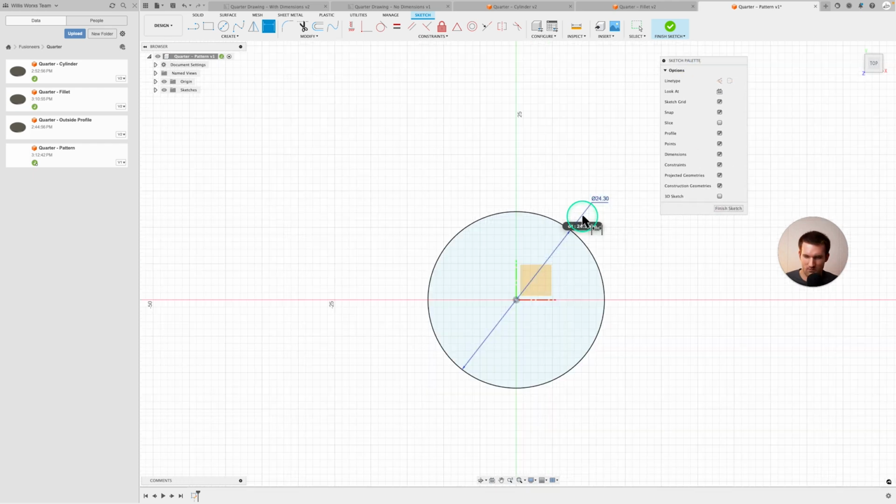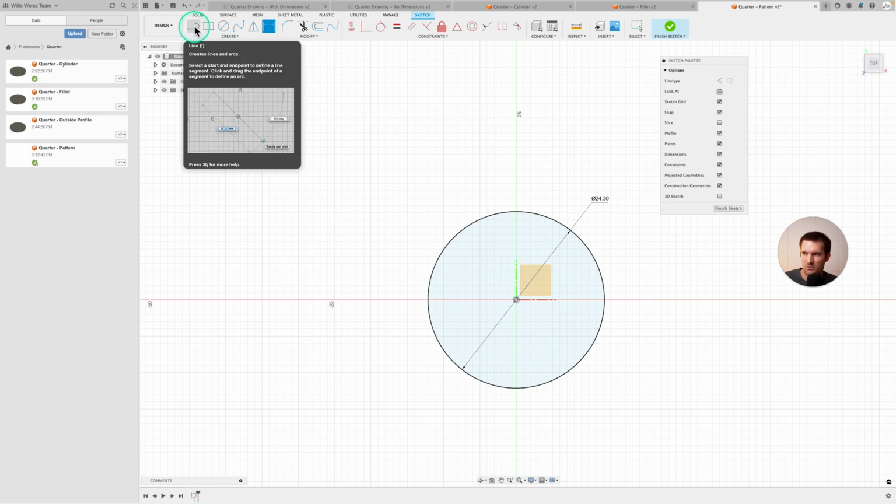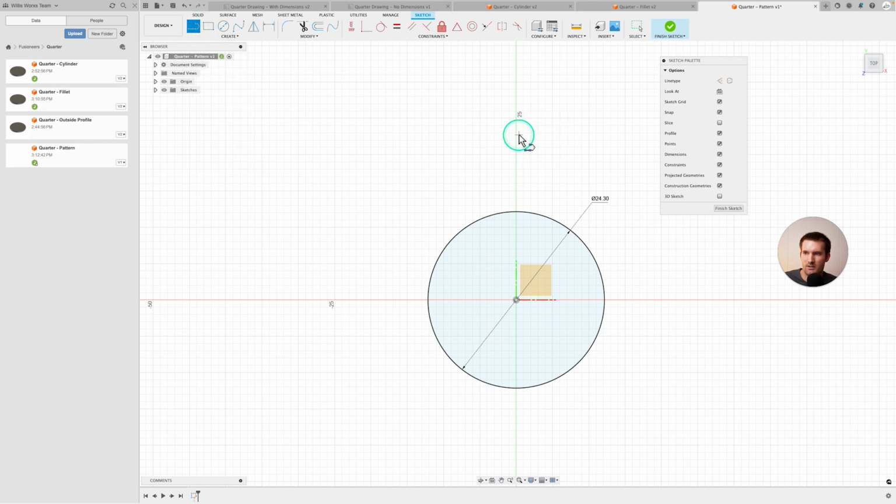Now, if you think about making a pizza, how would you do that? So you want to draw a line, right, to kind of section off your pizza. So the next thing we can do is we can select line, which is also L on the keyboard. Again, line starts with L, so L is the shortcut. So we're going to click line, and then you'll see kind of the same thing pop up again. So let's select the center, and now let's just draw it kind of out to the side, and then you'll see it snap. So this one will actually kind of automatically constrain itself, but just for an example, I'm going to give it an angle like that. Okay, and then I'm going to draw another one kind of at a random angle again.